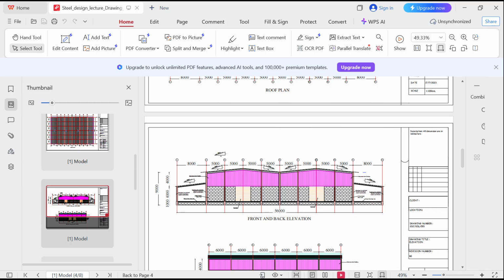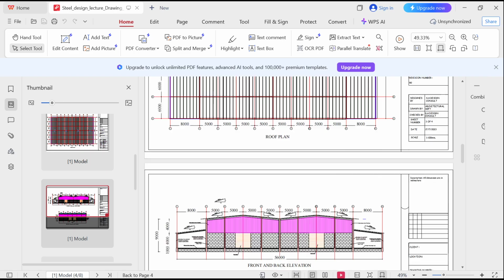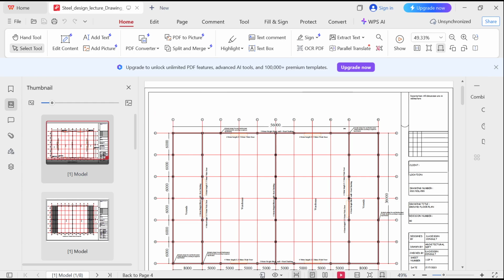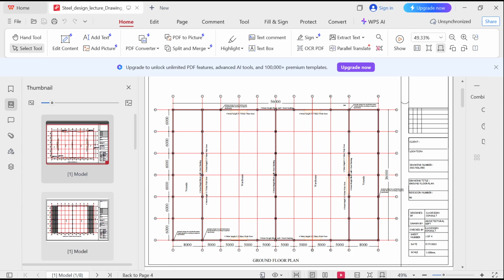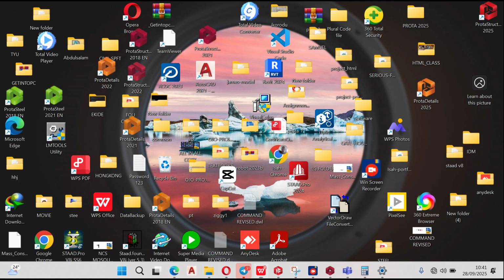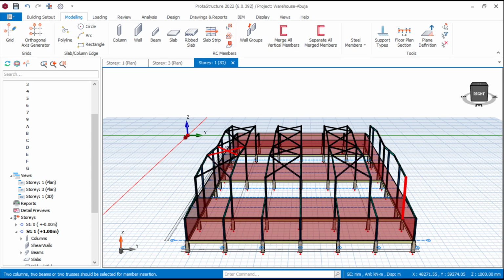So now let's put bracing also. I will leave the longer side, I won't brace it. For that one, I'll be using a moment connection to resist the forces. But for this one, where we don't have any doors and it is not hindering anything, I'll be bracing it. Now let me show you how we are going to go about that.